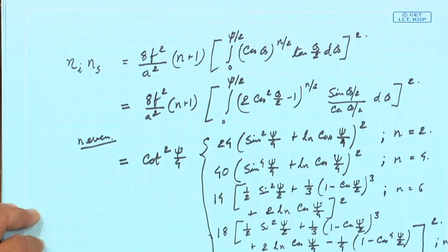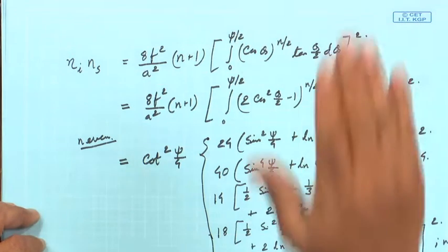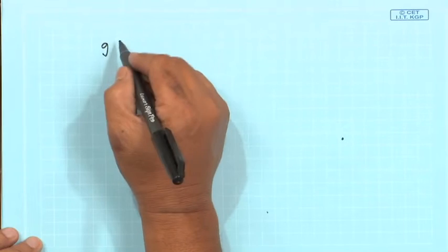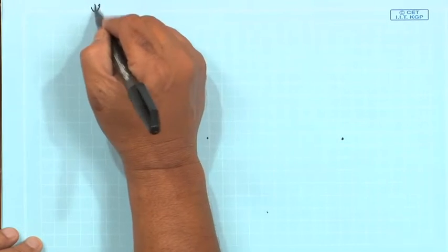Now, while deriving all this, we have assumed uniform field illumination in the aperture, but obviously with a cos to the power n theta type of excitation, there will be taper. So, what will be the taper, that also we can calculate, that is, what will be the amplitude taper in the field. So, let us say that we have chosen from this figure some optimum psi value.